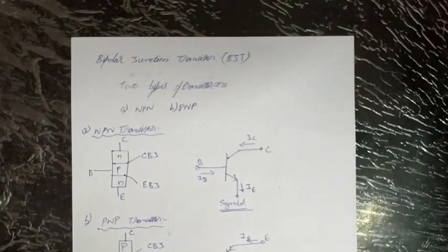In previous sections we saw PN junctions and the Schottky diode. Now we have the bipolar junction transistor, which is called BJT. What is a transistor? A non-linear three-terminal active semiconductor device where the flow of electrical current between two of the terminals is controlled by the third terminal. The name is an acronym for transfer resistor. Transistors may be used in circuits such as amplifiers, oscillators, detectors, switches, and so on.